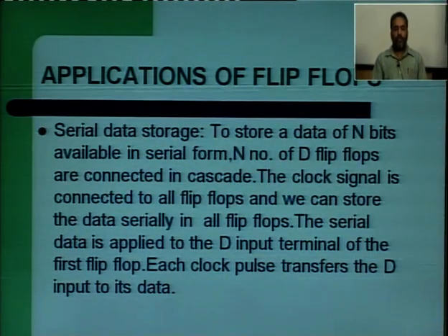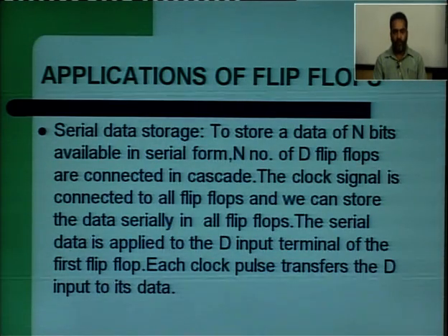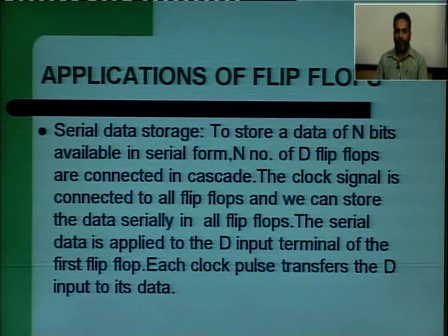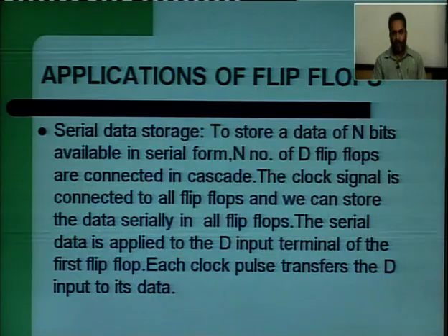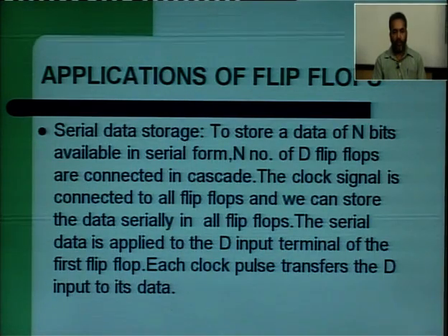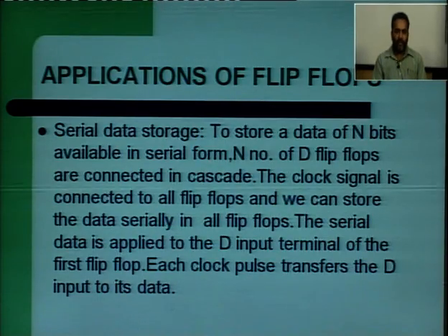Now, next, serial data storage. Again it is a storage application. Storage application means where the flip flop is used as a memory device. Again here D flip flops are used, to store data of n bits available in serial form. N D flip flops are connected in cascading form. Cascading means one after another. The clock signal is connected separately to all the flip flops, and we can store the data serially. So, like this, the data is stored serially in all the flip flops.